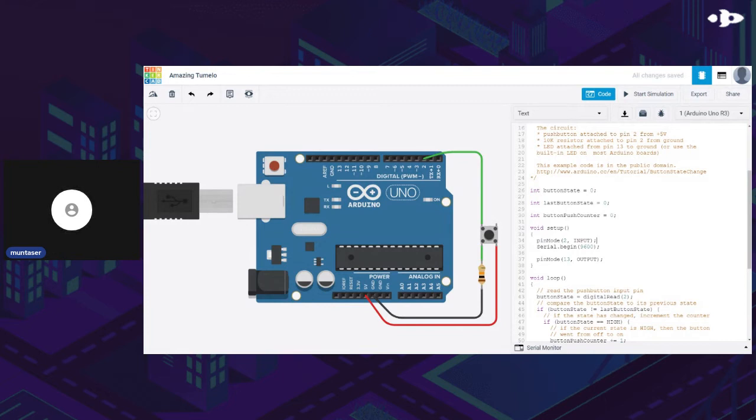So the way the Arduino can communicate with the outside world, apart from sending a signal on one of its pins, is when you have a serial port or this guy connected to your USB. This is actually a serial connection. So this interface can send things like strings, numbers, integers, and even raw bytes.